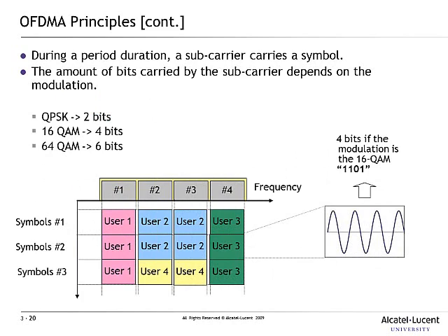And the basic idea in OFDMA is that we have this idea of a subcarrier. So it's a sort of an evolution of FDMA, but we have brought the subcarriers even closer together, and I'll explain to you in a few minutes how that was done. So basically, we talked about a symbol before. We said in QPSK, one symbol represents 2 bits. In 16 QAM, a symbol represents 4 bits, and so forth. Now, each symbol is transmitted on a subcarrier.